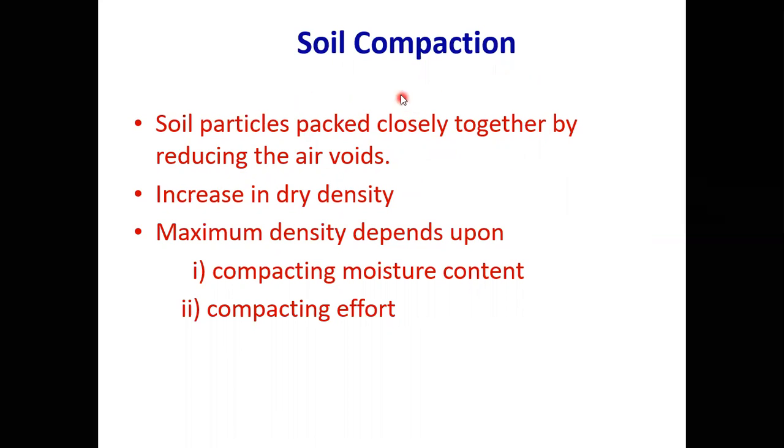That means in compaction, what we are going to do is apply some external force so that all the soil particles get compacted or packed closely to each other. So in compaction, basically we are going to remove the air voids by providing the external force. That means you apply external force so that the air voids are removed. Once the air voids are removed, the density of the soil is increased, or the soil particles get compacted or